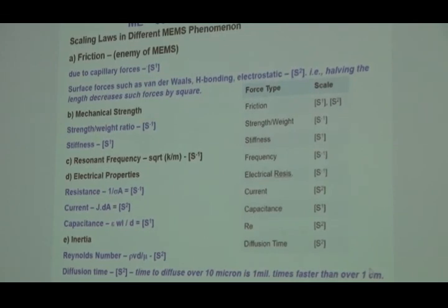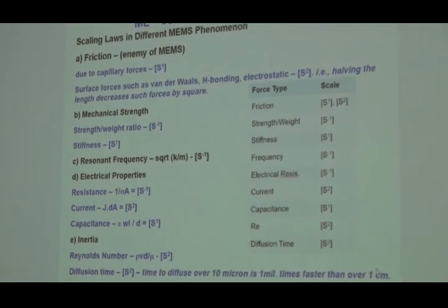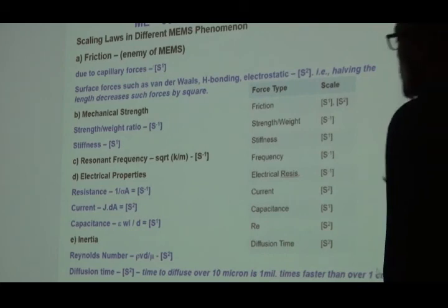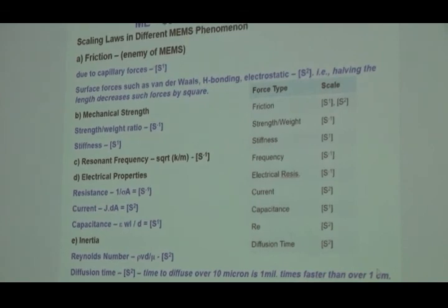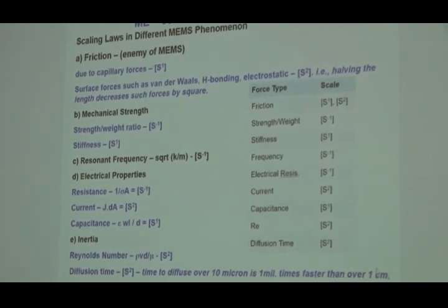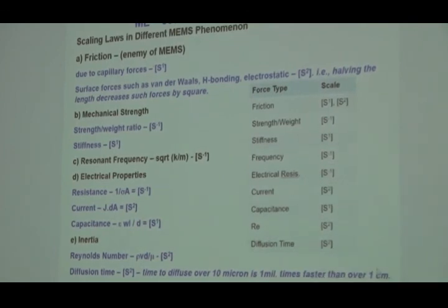In fact, if you want to mix things, it becomes difficult. Turbulent flow is actually good because it mixes things up. So when you're trying to mix two liquids, you can't mix them just by having them flow or increasing the velocity. You have to create some other designs, which we're going to cover some other time. The point I'm trying to make here is about device design, device selection, physics selection. Scaling laws have a tremendous impact. And if you pick anything from this class, it's about always going to first principles. Okay? All right, any questions?